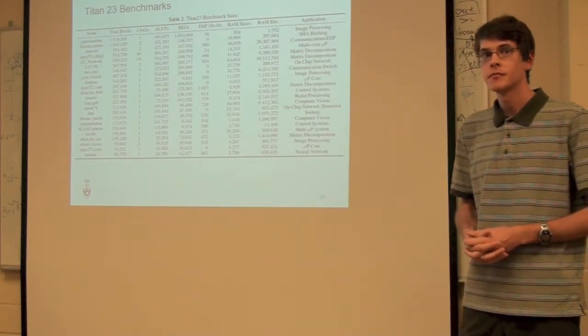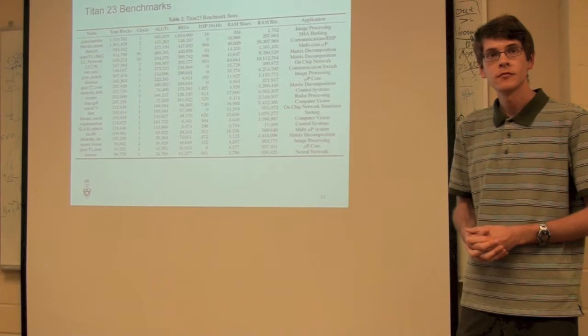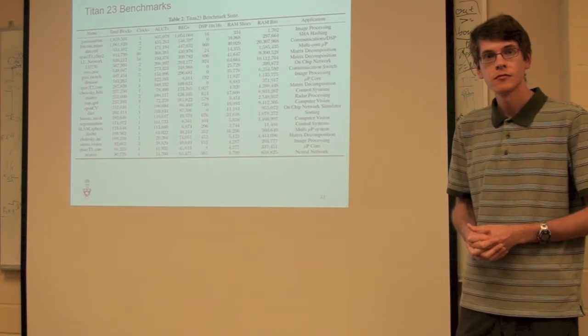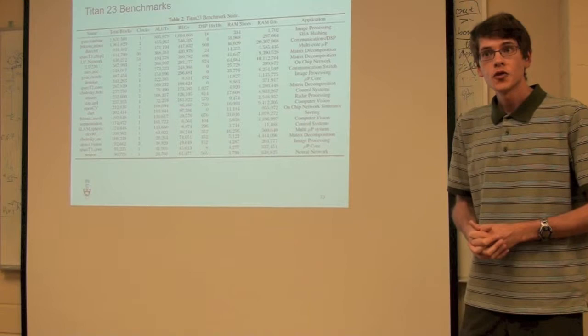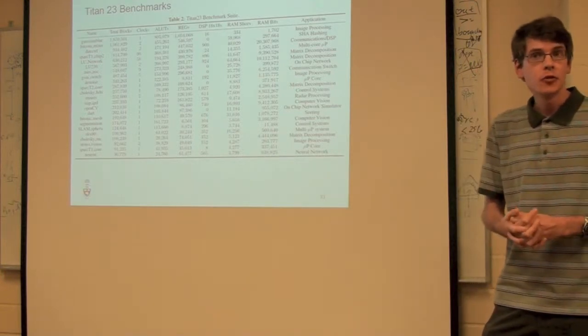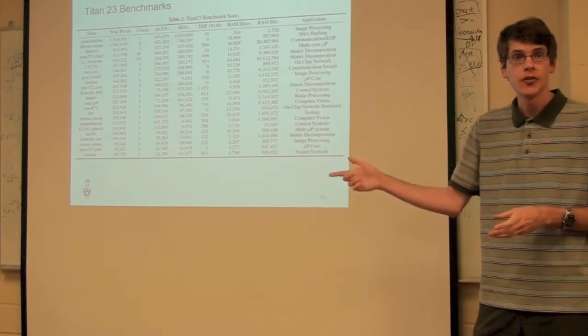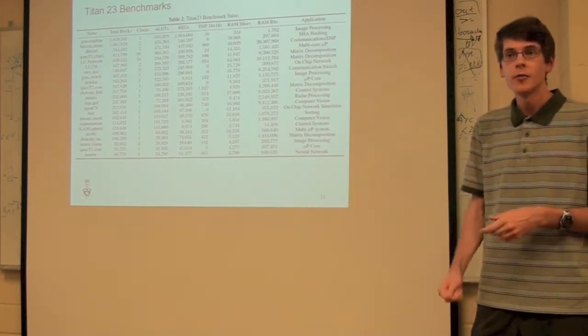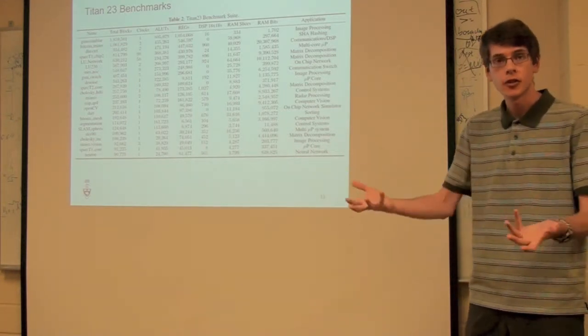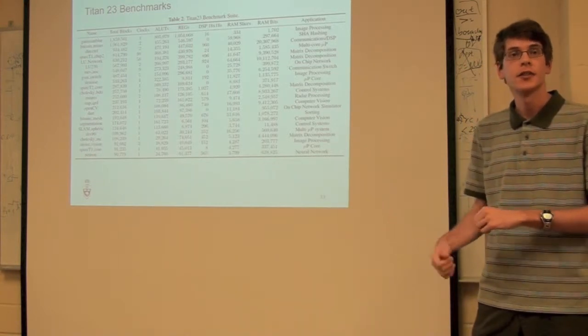That's cool. Can you play with the hard blocks and convert Quartus to, say, just give me this in soft logic if you wanted a different version of it? So yeah, for instance, if you use multipliers, Quartus will typically just infer those into the hardened DSP blocks. If you tell Quartus to infer them into soft logic, they'll come out as soft logic in the netlist.